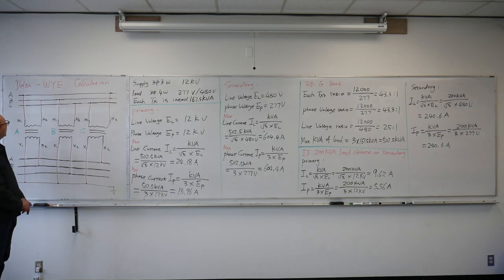It differs from any other Y, delta, and the Y delta. For delta Y, you can see on the low voltage side, the Y side, all the X1 is connected to the neutral conductor. That's as our phasor diagram indicates.